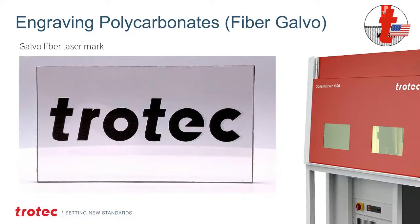Also, thickness, I didn't mention thickness of cutting can be limited as well by wattage. The stuff I was cutting, I was cutting with an 80-watt laser, and I was only cutting 3 millimeter or close to 1/8 of an inch of material. So you saw the speed of that. The speed of that cut you saw earlier was at regular time too. There was no time lapse on that.